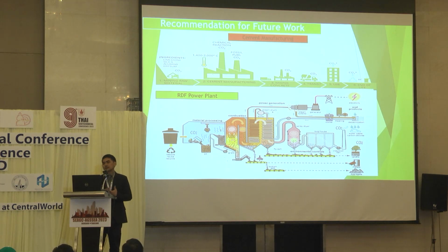And the recommendation for future work is that fly ash from municipal solid waste can be a sustainable construction material. The future study should try to reduce the quantity of cement used in buildings and repairs as much as possible, with supplementary cementitious material, to support Thailand's future cement demand while lowering the cement industry's greenhouse gas emissions.